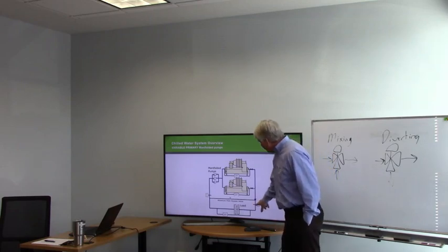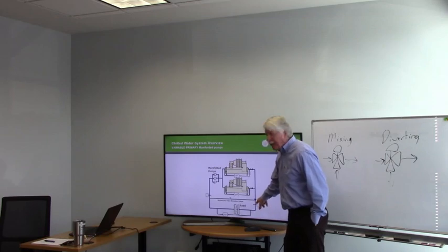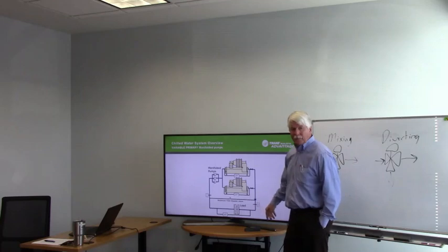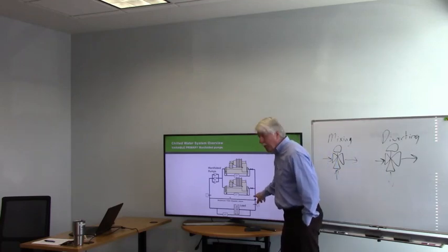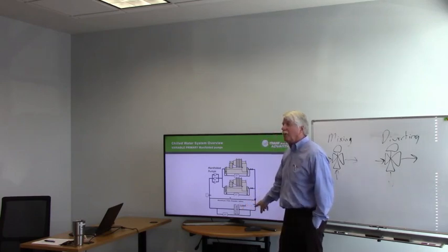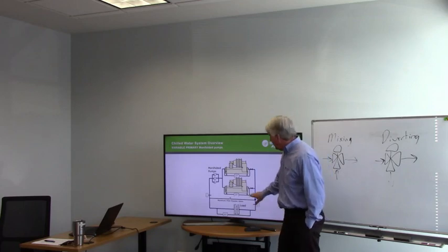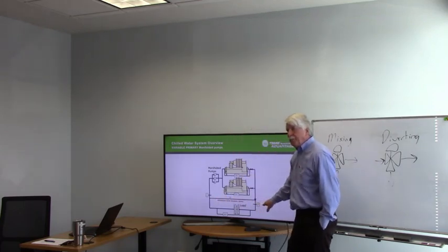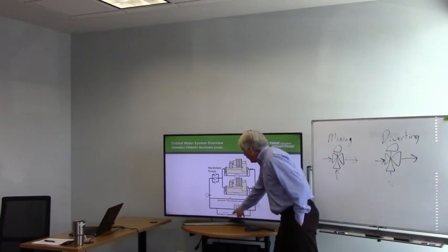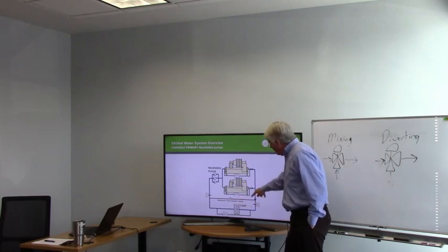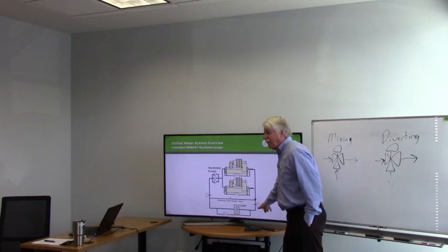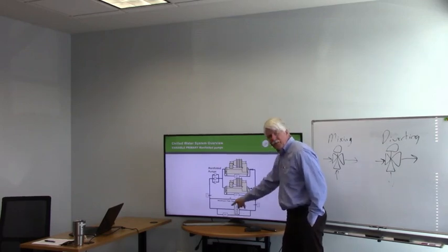Now, the supply temperature I'm showing on this side of the bypass, and in a variable primary system, it doesn't make any difference. It could be here or here, because water flow is always that way. What becomes extremely important is if you have a primary-secondary system, and this is a decoupler line. When this load goes up, you're going to have water coming backwards through here, and you could be making 42-degree water with the chillers, and this might be 48-degree water going out to the system.